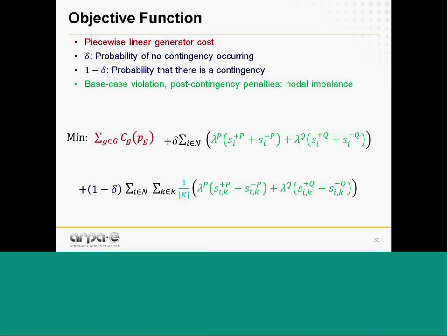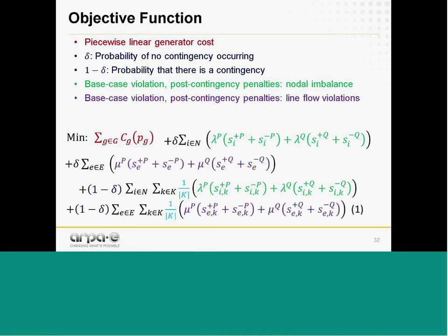And this is going to, again, be there. The relaxation associated with the pre-contingency node balance, post-contingency node balance. There are also going to be relaxations relative to the limits on the lines, or you could say limits on transmission elements. You don't only have lines, you also have transformers. And they're going to have their own penalty prices as well, driven by industry practices and slack variables.